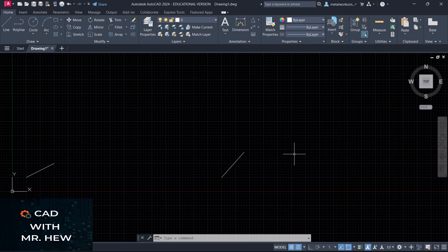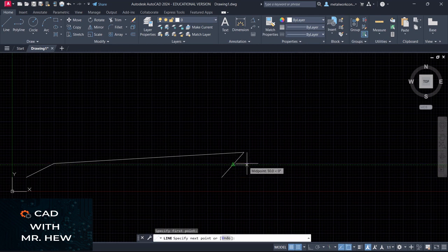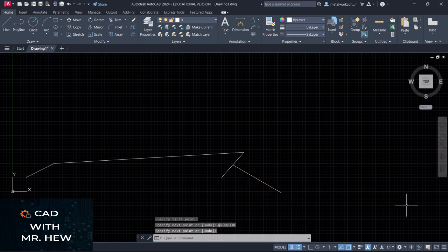You can draw it to. So I could draw a line from here, then from there to that point. Enter. I can draw a line from here, and we're going to draw it down here. Now, remember, AutoCAD is measuring 0 degrees this way, so we'd have to measure all the way down here. So we're going to type at, relative to that point, 200 millimeters long, less than sign, an angle. I'm going to put 330. Enter. Press enter to close the last command.